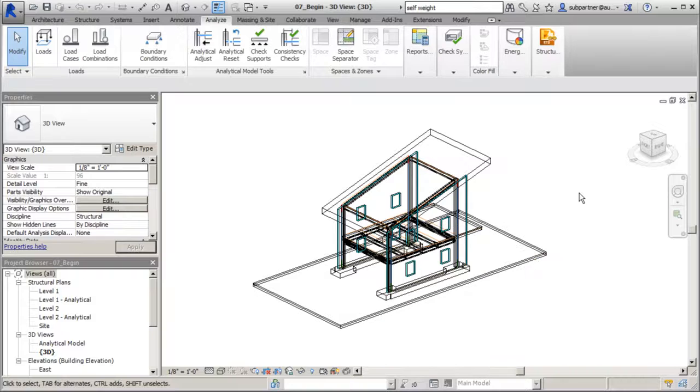So whenever you're running your analysis, make sure your loads are in place, but two, make sure everything has material with physical properties. Now I think we applied material with the physical properties to our floor, or both of our floors, but we didn't do it to our wall because we assumed it already had it because it was a structural wall. Well, now this is a really good exercise on how we can get this accomplished.